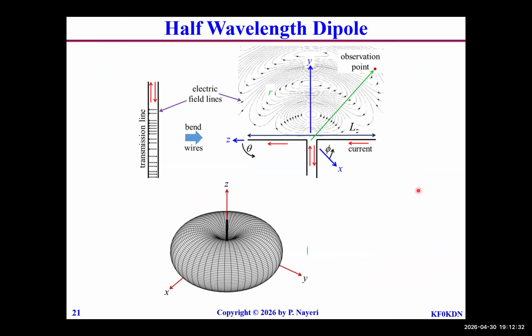So your typical half-wavelength dipole, as mentioned, you're typically going to feed it with a wire, with a transmission line here, and commonly you're going to have a balun to ensure a good matching. Keep in mind that mismatch would occur in the case of a dipole. If you have your dipole here, the typical dipole would have an impedance of 73 plus j42.5 ohms.